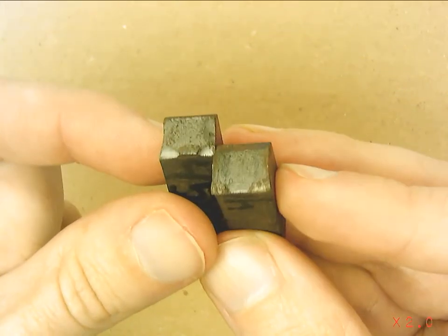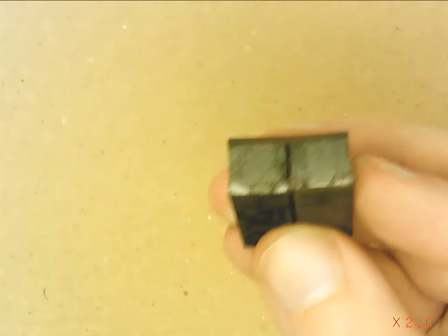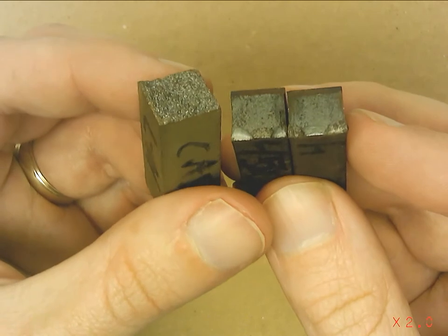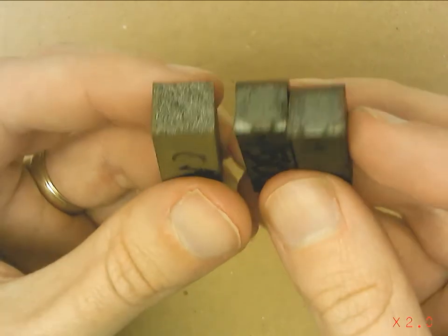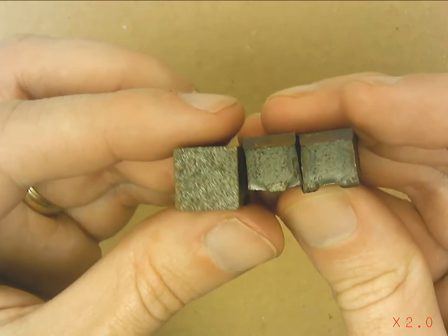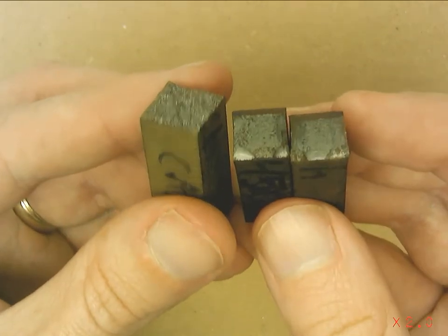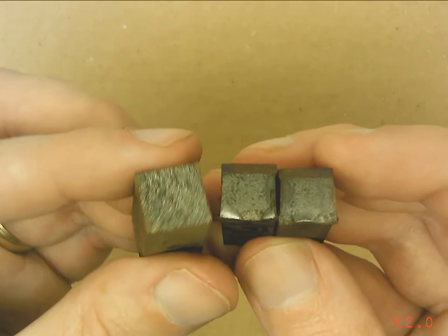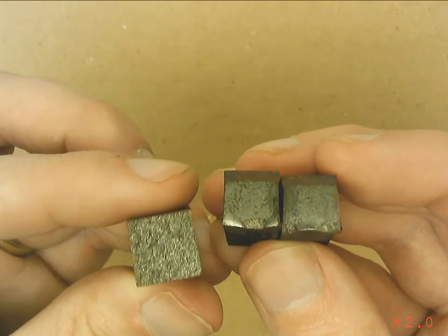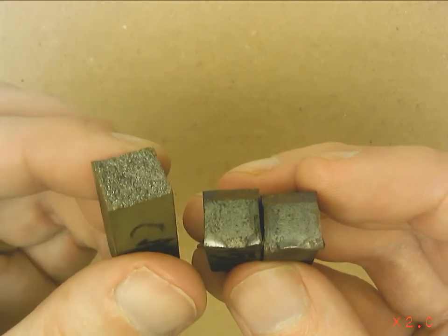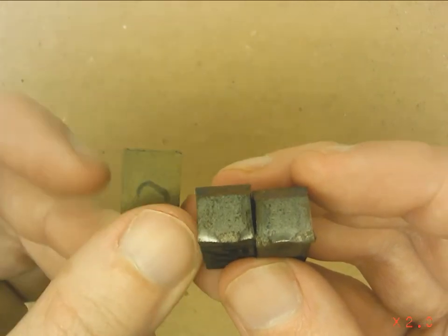Okay, they are not particularly sparkly, not when compared to, say, cast iron. This is a non-standard sized cast iron sample. It's larger, it doesn't have a notch, but you can see there are sparkles on the surface, and that is characteristic of a very brittle failure.